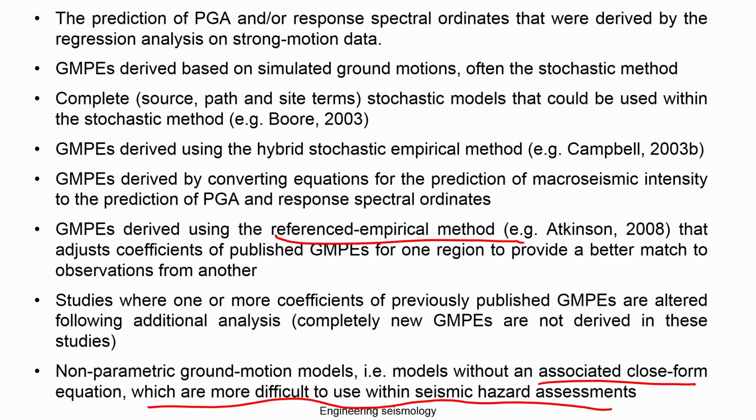That kind of study is important. We do selection of ground motion prediction equations by doing efficacy tests like the log likelihood method, the log likelihood analysis, where you do systematic mathematical and statistical analysis using available data, and then find out which equations are suitable for what distance range and magnitude. That can be further used for hazard prediction, so that the hazard analysis is more accurate. That is what we have also done.